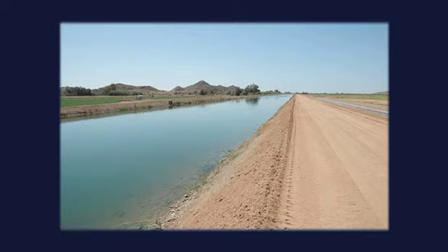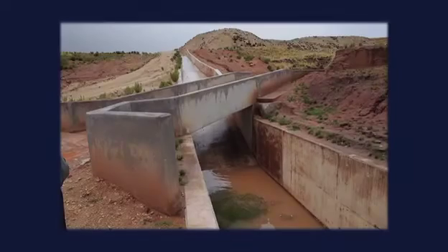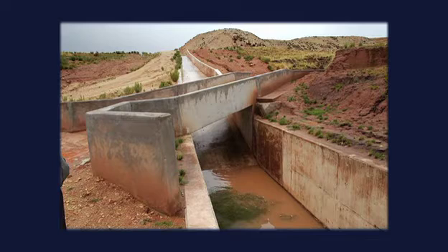A prismatic channel has a constant bottom slope and a constant cross-section. The channel section is normal to the direction of flow. A trapezoid is the most common cross-sectional shape. For an unlined channel, it provides bank stability. Canals built of stable materials such as concrete can be of rectangular shape. Triangular channels are used in ditches and roadside gutters.